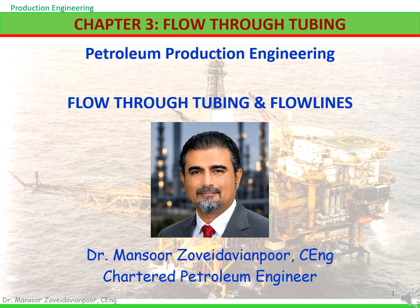In Chapter 2, we learn how the reservoir delivers fluids into the wellbore using the Inflow Performance Relationship, or IPR. In this chapter, we continue the journey by following those fluids to the surface through the tubing and choke. We'll learn how pressure losses affect production, introduce vertical lift performance, VLP, and combine IPR and VLP using nodal analysis to determine the well's actual operating point.